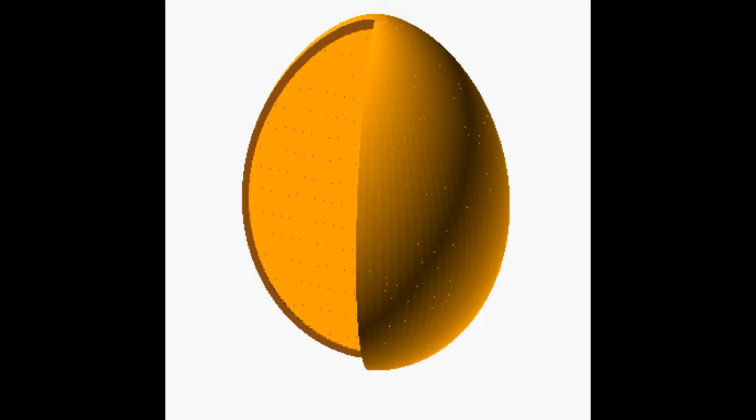The engineering problem is to determine the rate of heat transfer across the eggshell. Now, I have never taught you how to calculate the rate of heat transfer through the eggshell, because the eggshell neither looks like a plane wall, a long cylinder, nor a sphere. But we will approximate the shell as a plane wall. The engineering assumption may not be suitable for the whole geometry of the egg, but it is interesting to know how good the geometrical simplification is.